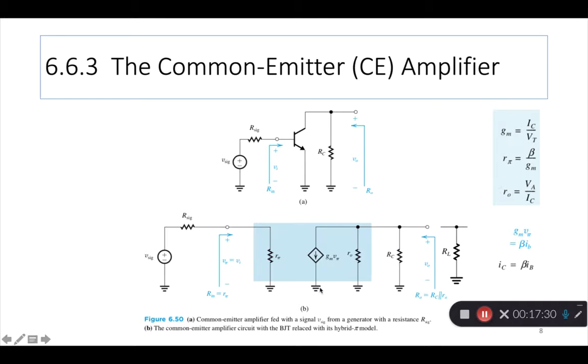Finally, the RO, the output resistance, is VA, which is related to the early voltage, you may remember. So RO appears sometimes, but not all the times in problems. But if VA is given, then you divide that by IC, the collector current, and you get RO. So these three in blue are your small signal parameters.